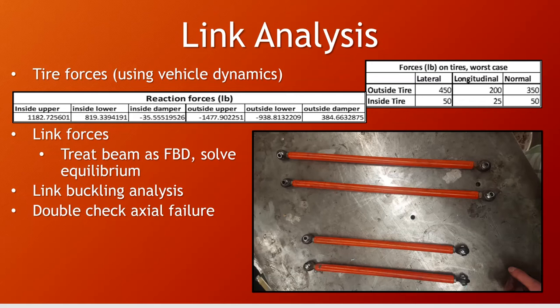The analysis shows the largest force the links will experience is a 1,500 pound compressive force. Using this to be our critical load, we then found a tube diameter and thickness that would give us a factor of safety over 1 while having the smallest cross-sectional area.